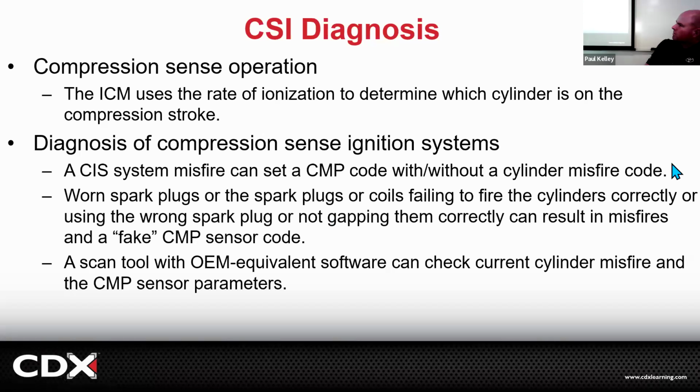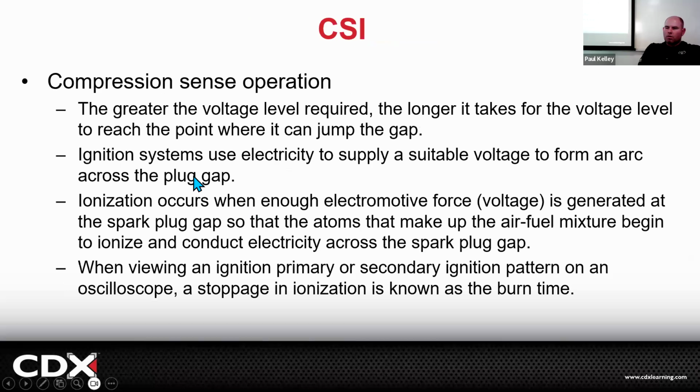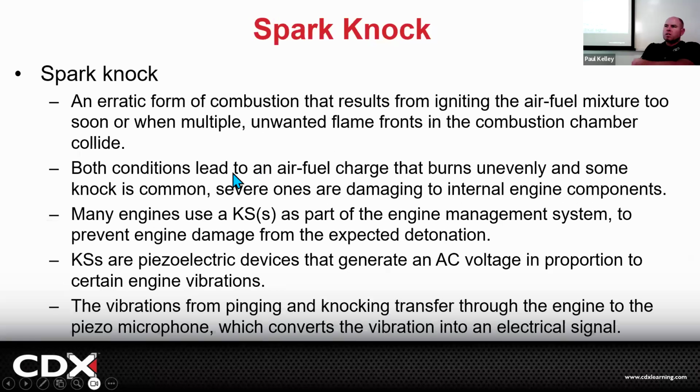Because I just talked about if this sees pre-ignition based on the ionization being early, it can tell that it's igniting too soon. Spark knock in general is when combustion will start in the cylinder, and then the actual spark will occur. A lot of times you'll have two flame fronts colliding. It'll make a knocking sound. Sounds horrible.